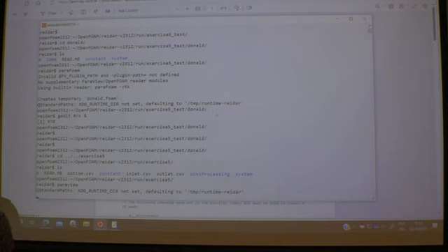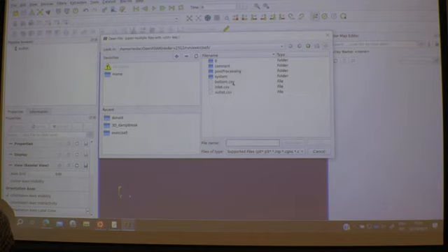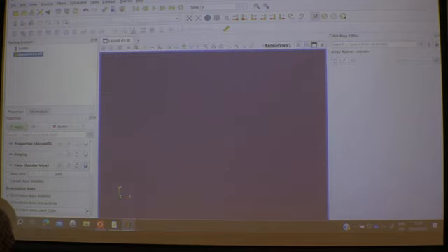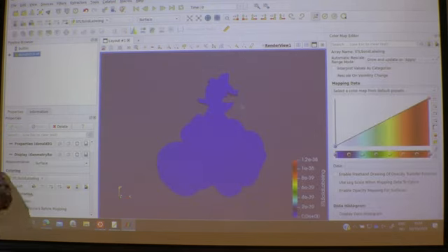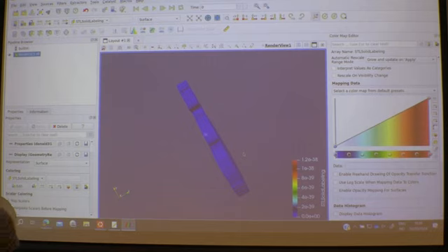ParaView. Here we have Donald. So this is just the STL file, nothing more. And as you can see, he has a depth in the Z direction already, given from the STL file I created. For the background mesh that you are creating, I would recommend you create the background mesh with a Z depth smaller than this one. So the mesh should be somewhere inside here.